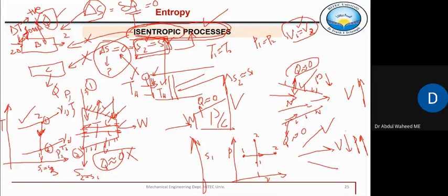But what have we assumed constant? Entropy. We are assuming that whatever fluid energy there was was fully transferred into work, and when it leaves, there is no entropy generated. During this process inside the turbine, no energy of this fluid is converted into heat or lost in friction. So whatever major portion of this Q has converted into work, no portion of it is friction. There are no irreversibilities. So such a process is known as an isentropic process, and that is represented by a vertical line.